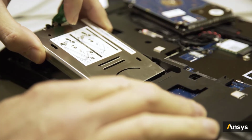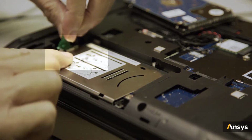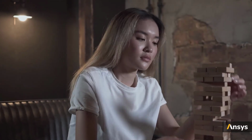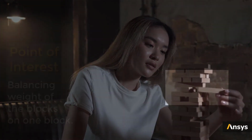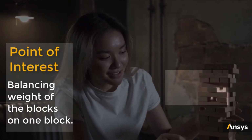But instabilities are not always life-threatening situations, and in some cases, they are not considered bad news either. For instance, a simple snap-fit mechanism that's commonly used in most electronics enclosures experiences instability at the point of engagement due to a sudden loss of contact. If you have played Jenga, you'll realize that it's played by strategically introducing instability in the structure, so your opponent would tumble it down while moving blocks in their move.